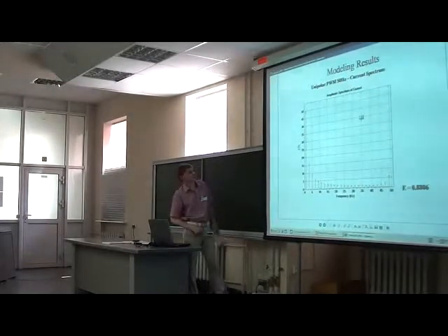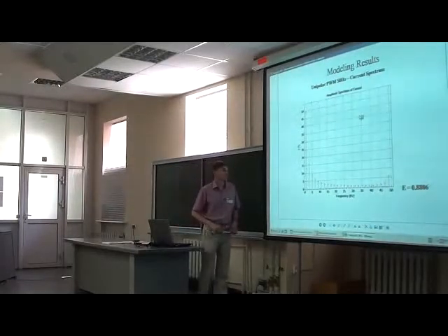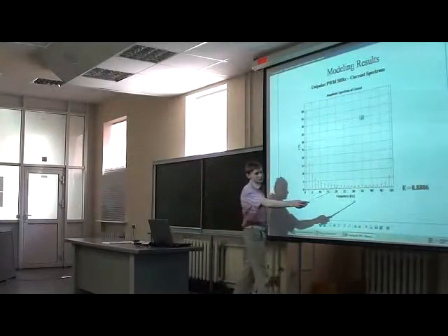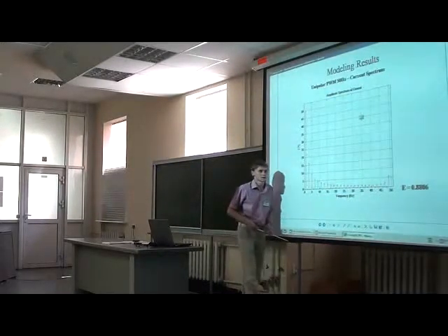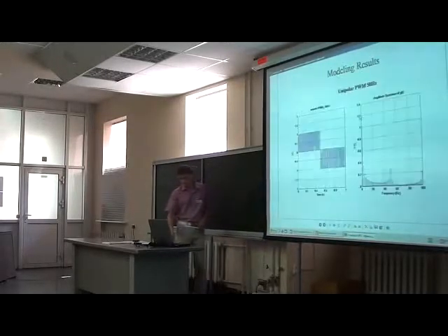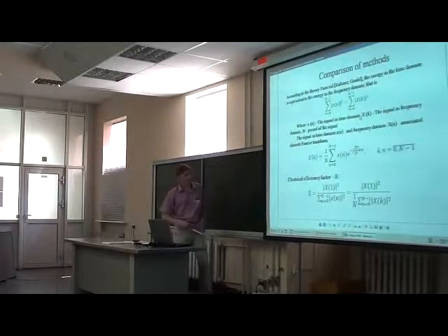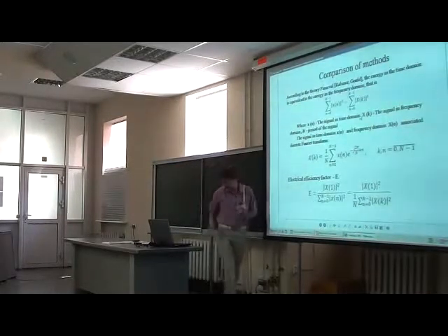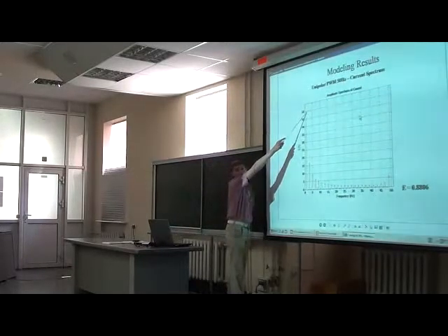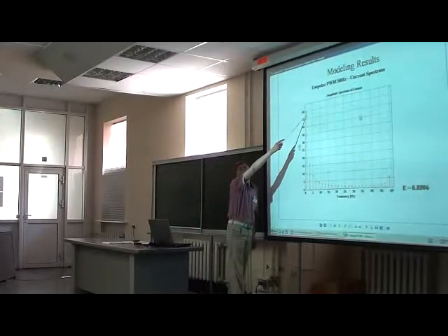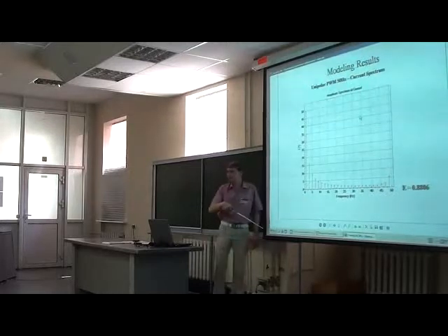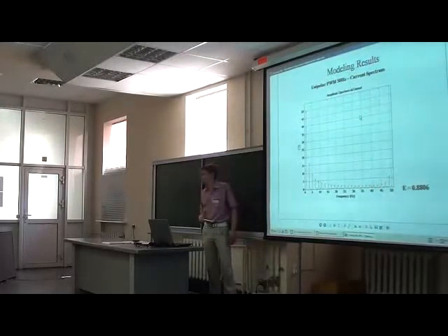This is the current spectrum of this method, and the electrical efficiency of this method is... Electrical efficiency is what divided by what? That is the current on the first harmonic to all the energy on all harmonics.